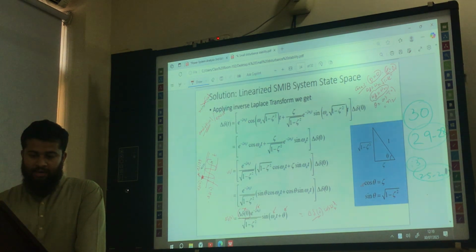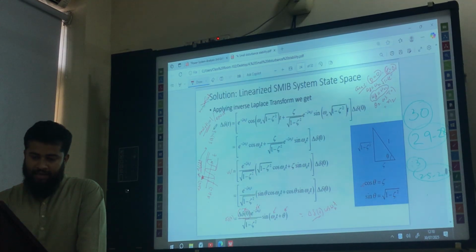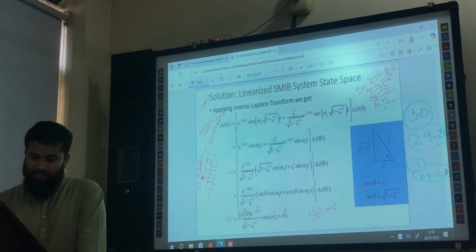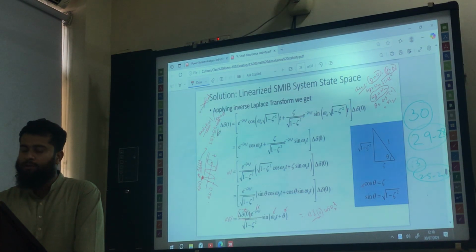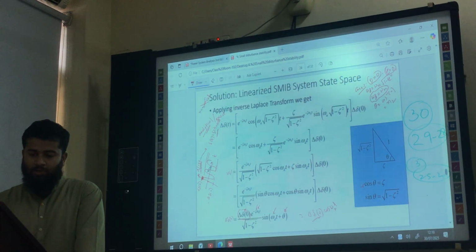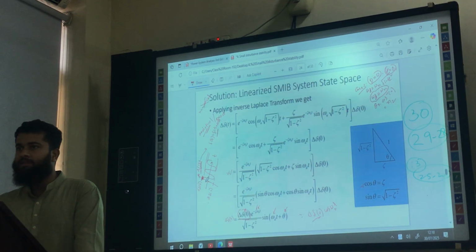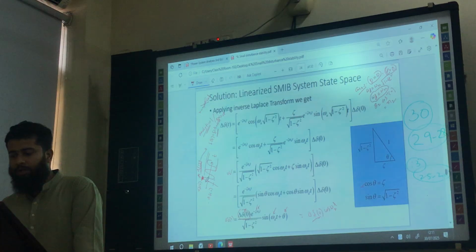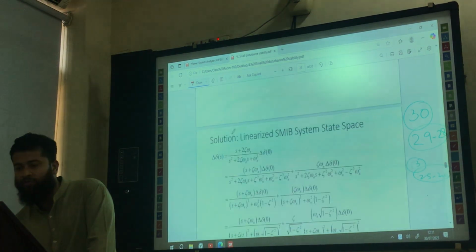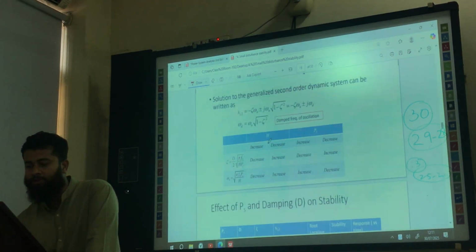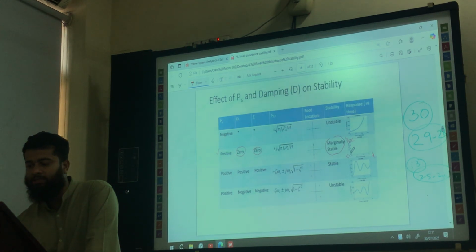So this is del delta of t. From this, you can also draw the shape of delta of t. How? You just have to add an initial value to this del delta of t. This will be a fixed value. So if you add this to this solution, the solution will be shifted upward. Then you will get this type of curve, where delta is swinging between, let's say, two fixed values like 51 and 70.